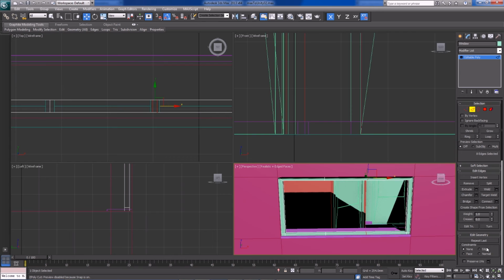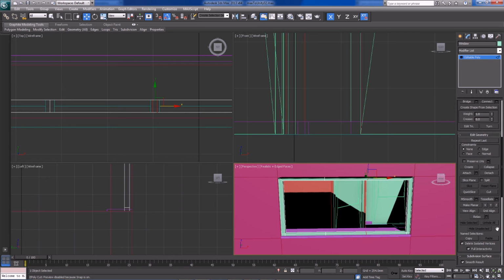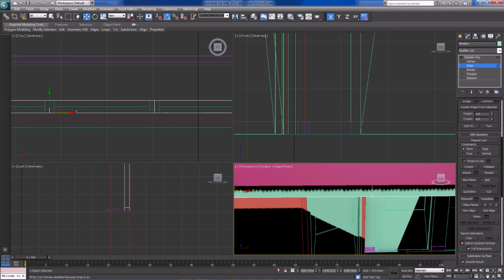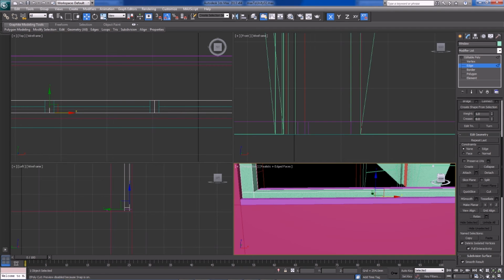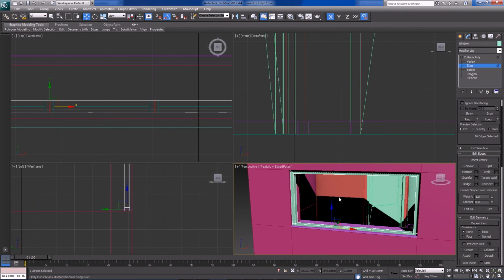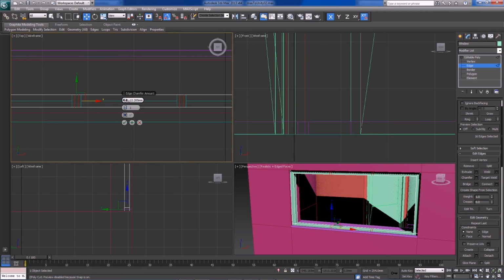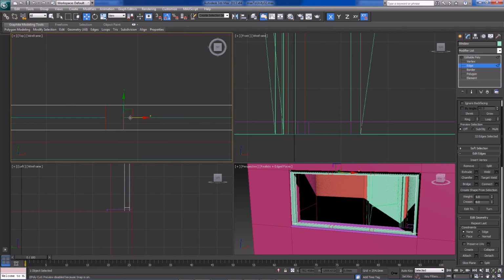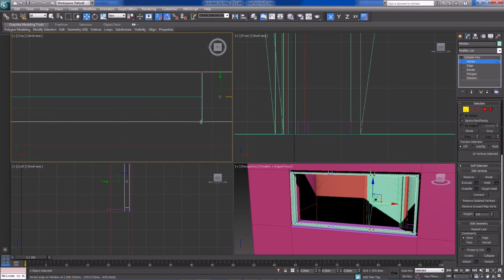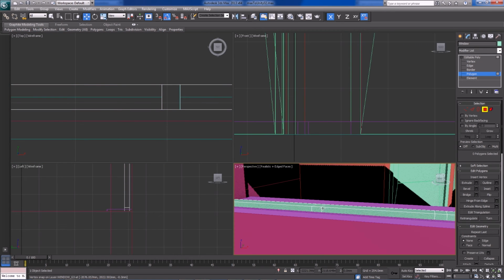These guys are not planar. Oh, that's why. So we can just make them planar again, this time on the x-axis. There we go. And this is where chamfer will come in useful. Let's just select these edges. We can loop them here, just because the edges are continuous, they actually loop around. So with those selected, let's keep an eye on here. If we chamfer them, they're 52, right? So they would need to be 25.5 to be exact. So there we go. Go into vertex mode, make sure they line up. And now we can bridge these faces.